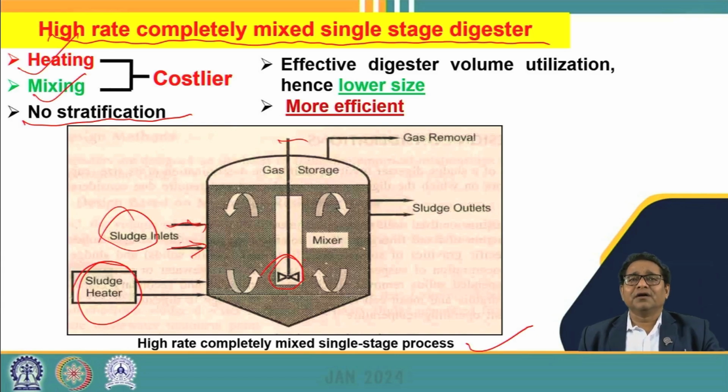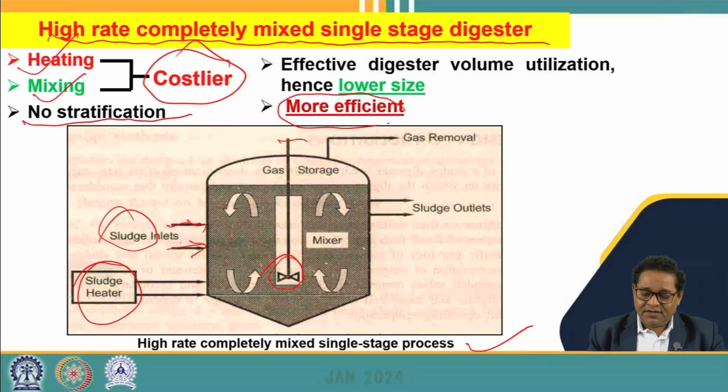If we compare with the standard rate digester, because heating is done and mixing is done, it becomes more efficient. But because a lot of energy is involved in heating and mixing, it becomes costlier compared to the standard rate digester. But in terms of efficiency, it will result in more efficiency compared to the single stage digester.